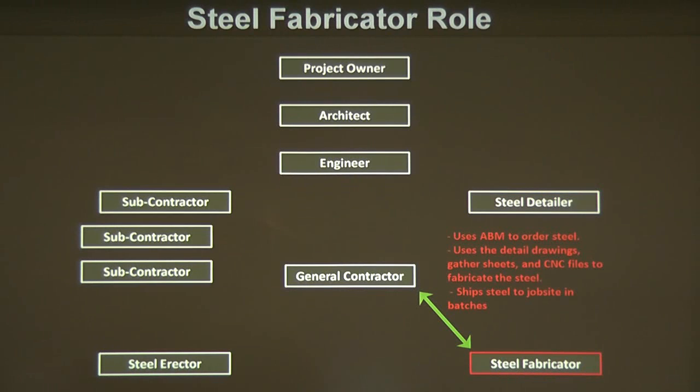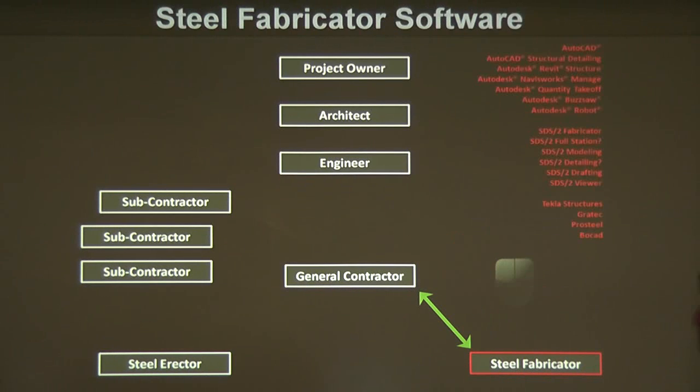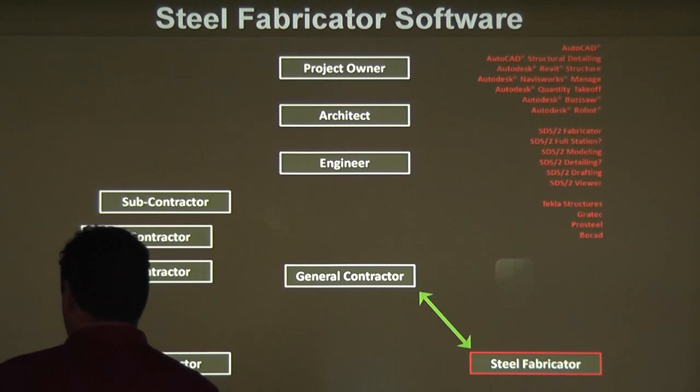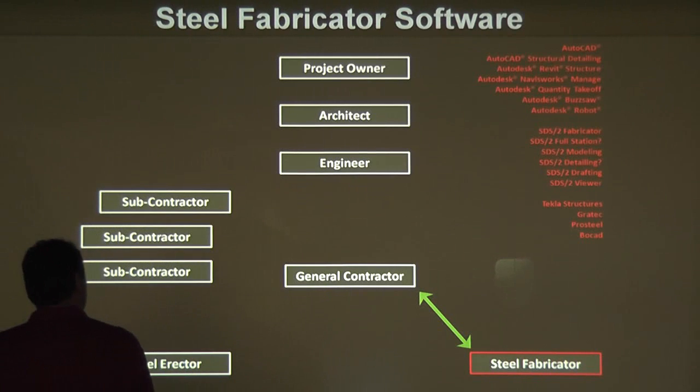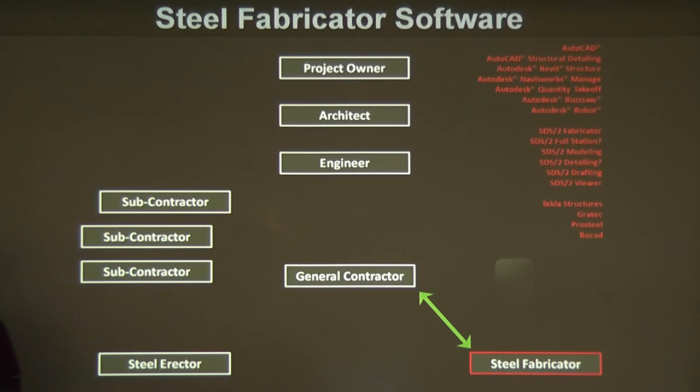Can you tell them what a detailer is? They may not know the difference between drafter, modeler, and detailer. Okay, good question. The question is, what is a steel detailer? The steel detailer is a profession, usually subcontracted to the general contractor, and they will take the design drawings that you guys are making from your Revit model, specifically the structural drawings, and they will take the structural steel and create manufacturing drawings, fabrication drawings, from that model using SDS2.